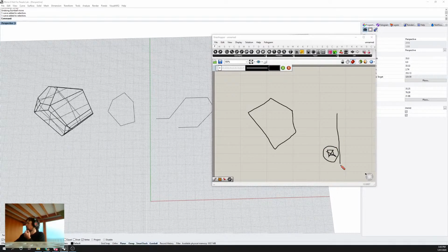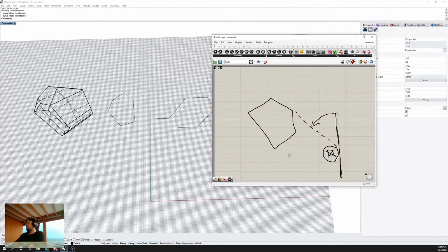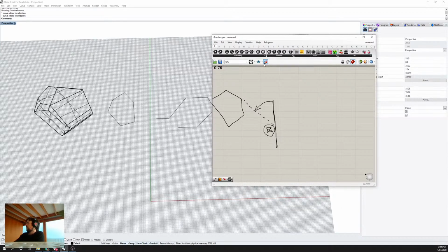We're going to have some sheet material or some stock material, so this is our part, and the bending arm is going to bend that part by some amount around the bender radius. And what we want to do is set up a hologram that shows us exactly what angle we need to bend that part to. In plan that's all pretty simple, and if we're just working with 2D parts, that's not overly complex. But if we think about this in elevation as well, let's say here's our bender, that's our bending axis, this cross, and we've got our part.